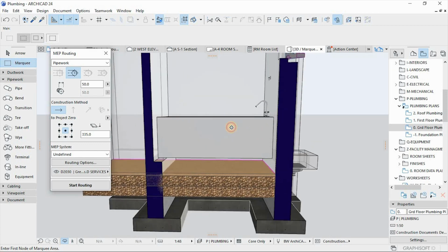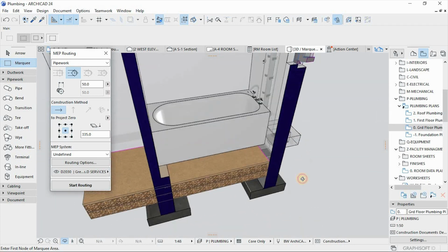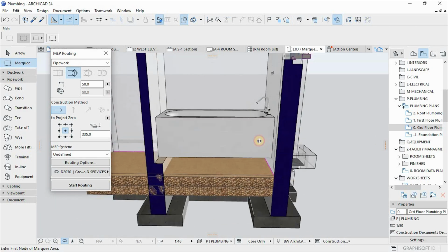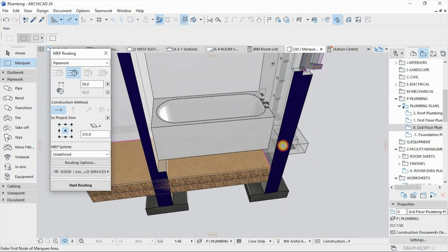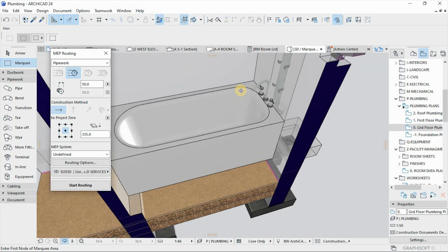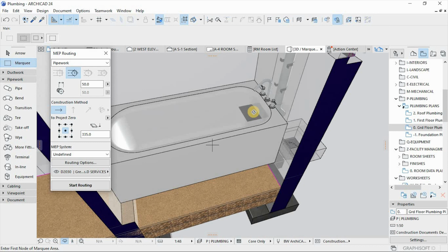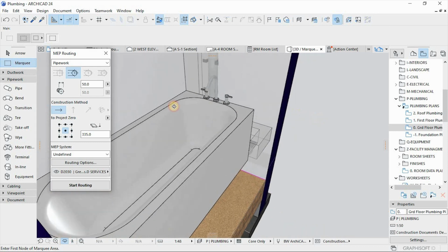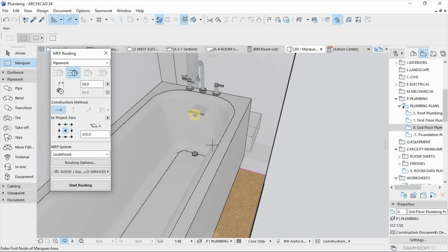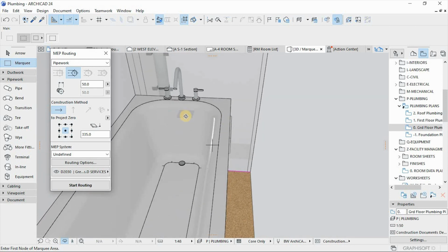The most important thing that you need to understand before we can even start placing items is the system, how it works. The drainage of the bathtub has two main components. The first component is the overflow riser, that is basically in this area here. Unfortunately, it doesn't show on this bathtub object.